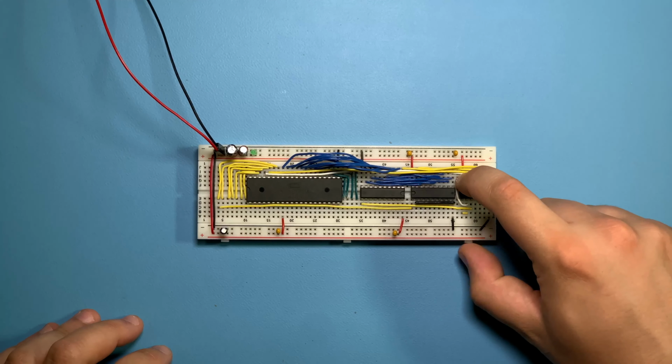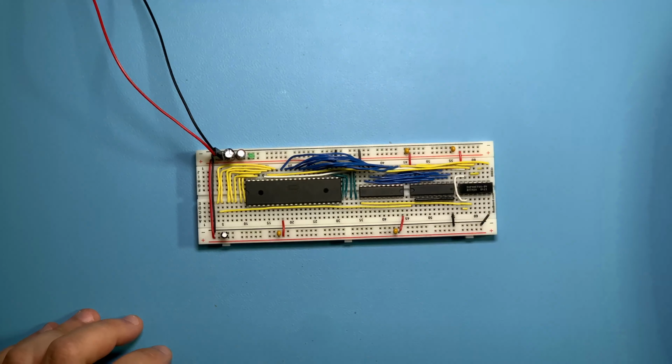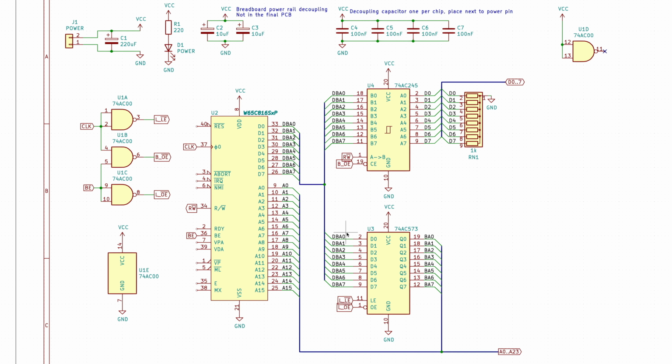So now that we have the behavior of the output buffers specified, remember I mentioned I would talk about the behavior of the latch again. So if you think about it, the bus enable pin is taking the outputs of the CPU to high impedance. So basically they become floating.